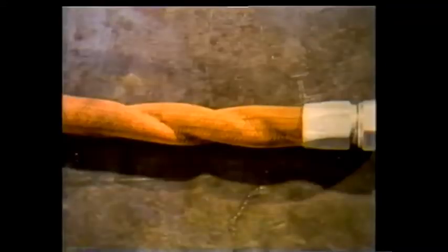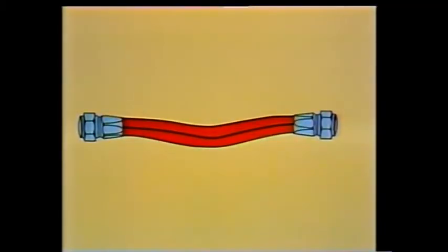The next step after selecting the appropriate hosing is, of course, installing it for operation. There are some simple but important rules to follow to ensure proper installation and an extended life for the hose. For instance, hosing should never be twisted as it is installed. Twisting can cause hose fittings to loosen, which could cause leakage when the system is in operation. Hoses should never be stretched when installed. A good rule of thumb is to allow an extra 5 to 10% of the total hose length for slack. This also provides for freedom of movement when system pressure is exerted on the hose.